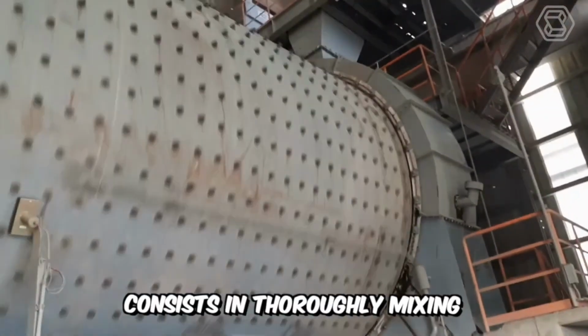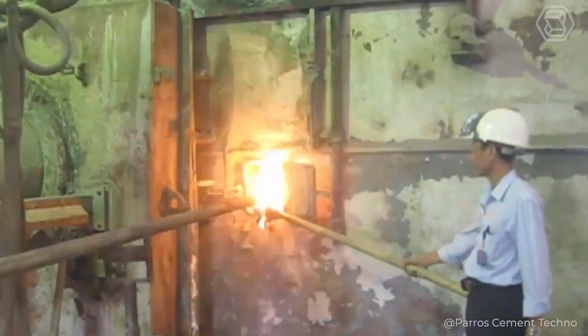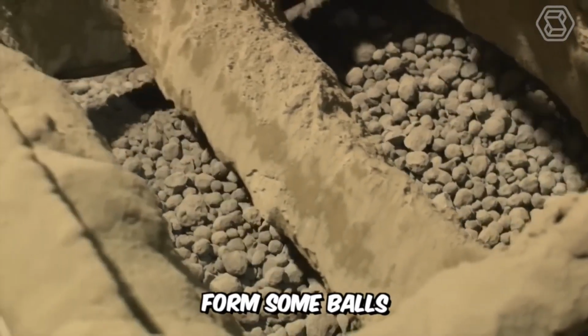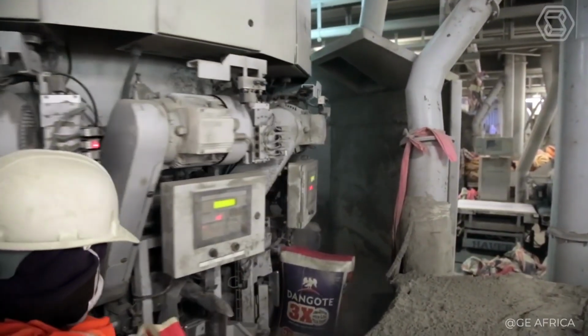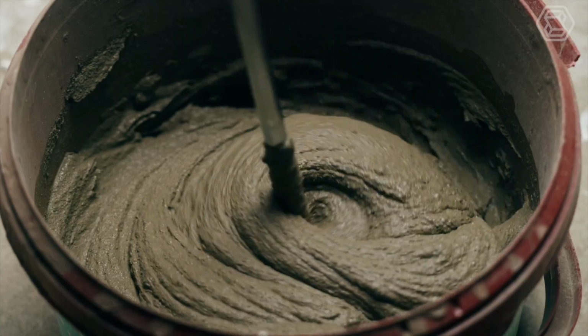The second stage consists in thoroughly mixing the clinker components in special containers, and this is also a critical process. After the work is done, the resulting mixture is fired for a long time in special furnaces, thanks to which all the components actively begin to interact. As a result, the lime and clay form some balls, the size of walnuts, and only then the components again need to be mixed and crushed. As for the technology of cement production itself, it definitely has its own peculiarities, depending on the method: wet, dry, or combined.